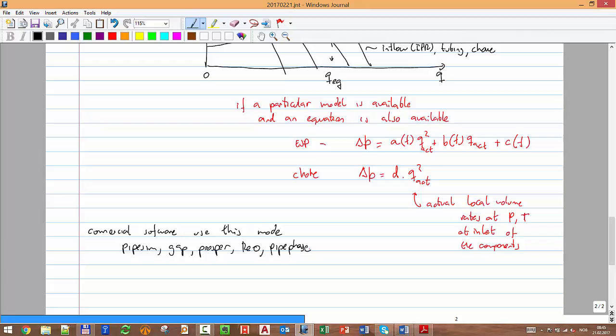But I'm going to tell you just now a question. So first, one main disadvantage is you need to have the model. Okay, you need to assume a model or find a model. So you need to do a pre-design. And for field development, that's really not so comfortable, because initially you just want to know if a pump, for example, will be able to help you, right? But you don't have the specific model of the pump. So this procedure in a way forces you to choose one particular pump model from the catalog.